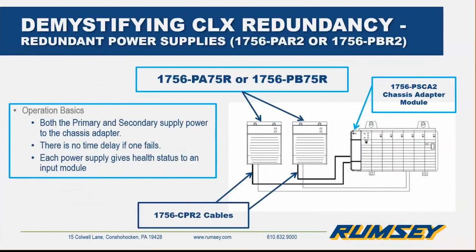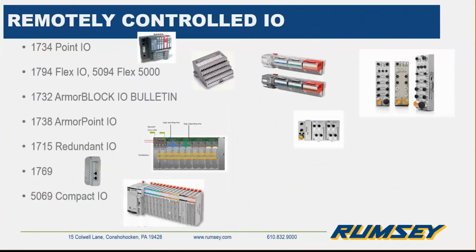Okay, if you want even more protection, even for a non-redundancy system, there are dual power supplies available. You have a chassis power supply adapter on the right, 2 power supplies. They're always powered at the same time. It's completely bumpless if one of them fails. And there's status or health wires you can connect to the power supplies. Do you recommend the redundant power supplies?